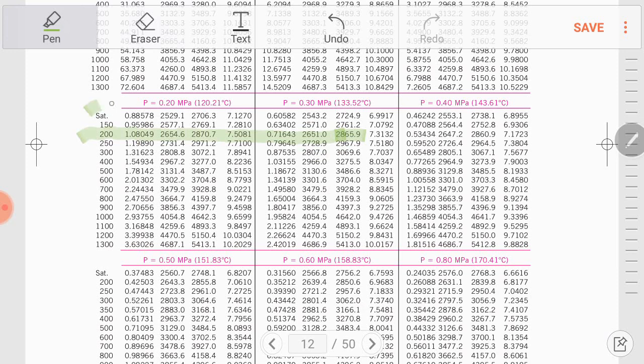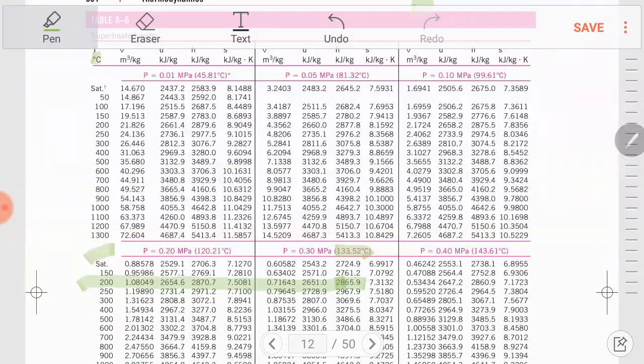The first one is saturated pressure, written over here. After that we are increasing the temperature with the increase of enthalpy. As we increase the temperature, the enthalpy will increase. So the final enthalpy is 2864, that is close to 2865, and across this the temperature is 200 degrees centigrade. Yes, the unit is degree.